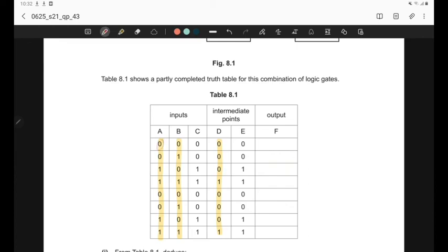So which truth table or which gate will give us a truth table like this? That means when both the inputs are 0, the output should be 0. Even if one of the inputs is 0, the output is 0, but we will get an output of 1 only when both inputs are 1. That means if we draw the truth table for this logic gate X, we can see different combinations of inputs.